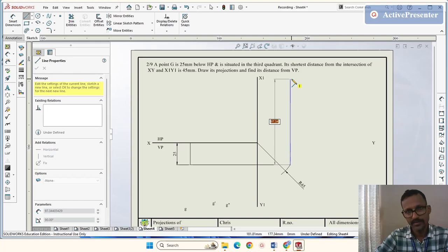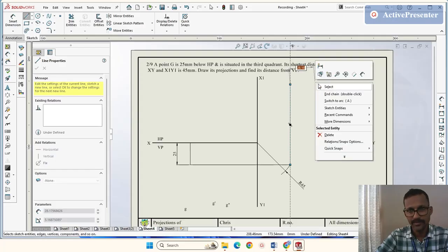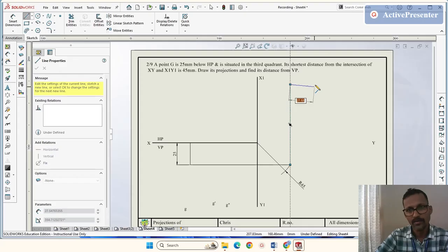Draw a perfect vertical line. Specify the second point of the line when the vertical snap is shown on the cursor. Deactivate the command, or you can double click to repeat the command.